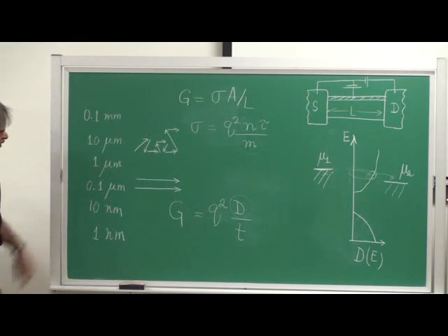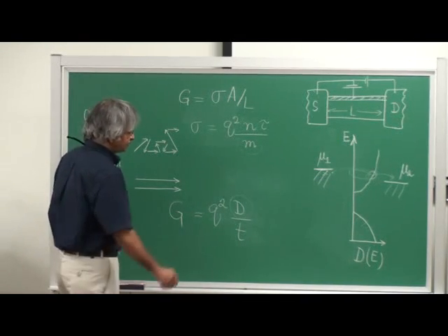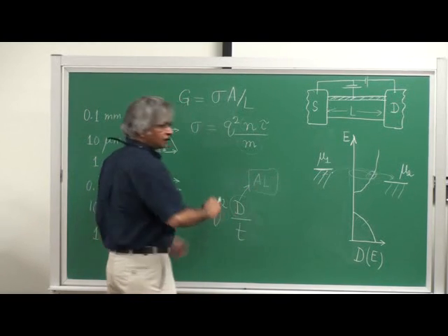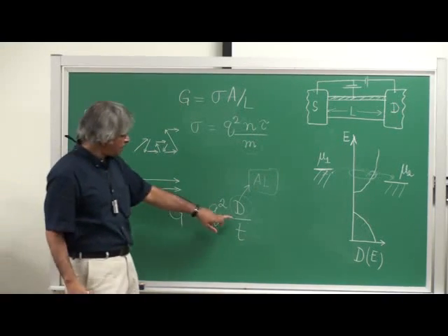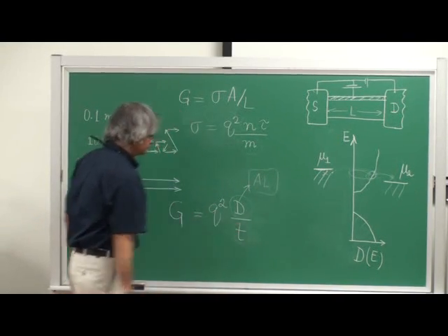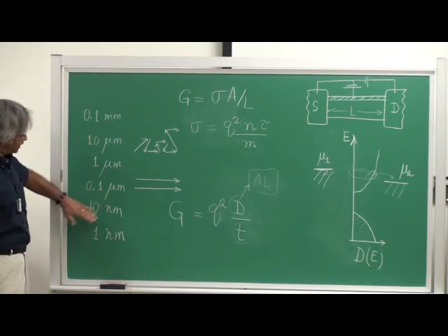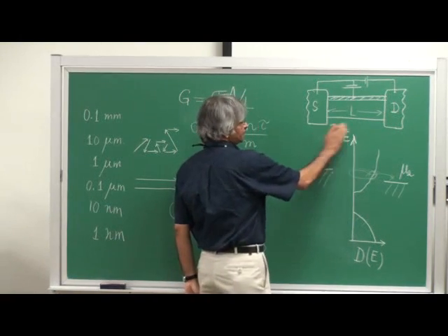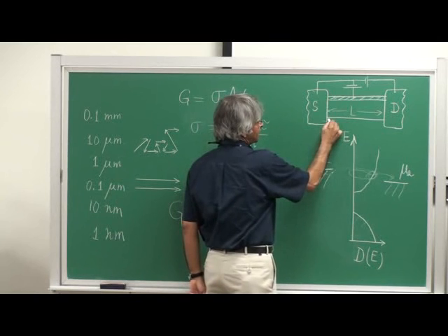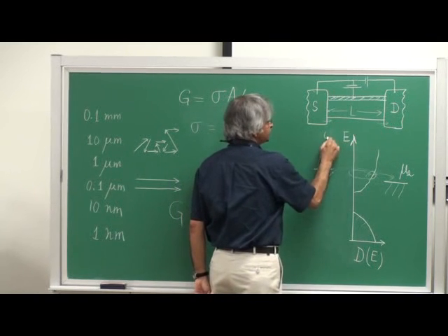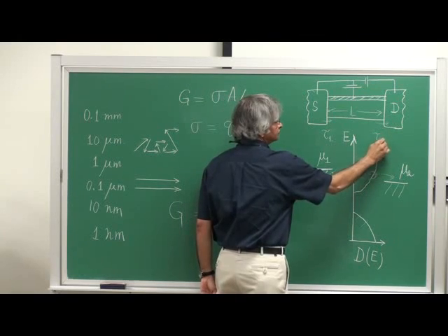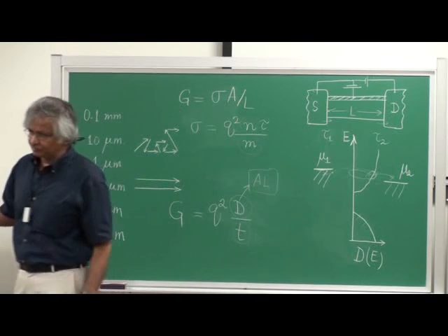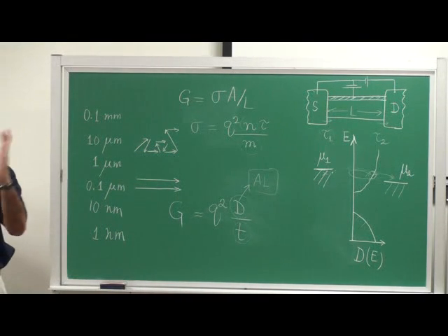So, for example, if you had a big conductor, then you would say the density of states is proportional to the volume of the solid, how big it is. And the time, of course, how long does it take? Well, in the very small conductor, I'd say that current is interface limited. Namely, what really matters is how easily an electron gets in and gets out, which I'll write as say tau 1 and tau 2. And so this would be what I call interface limited transport. So when you're dealing with really small things, what really matters is how easily they get in and out.